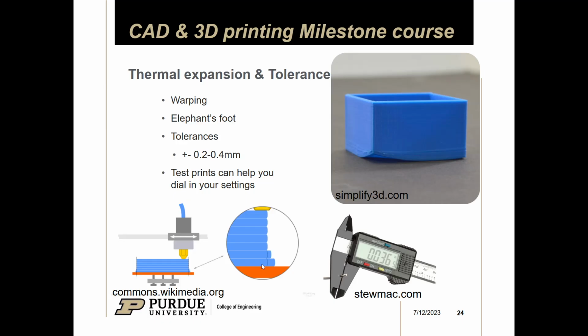Right? So I like to add chamfers to a lot of the bottom of my models whenever I print things, just in case the elephant's foot is a problem. I've tuned out most of the elephant's foot on my printer, but that's something to keep in mind. There's also elephant's foot compensation in the slicer that you use. So if you have a model without a chamfer on the bottom, you can add a little bit to kind of help. But if you're modeling already, it's typically easier to just add it there. So yeah, that's one thing you can do.